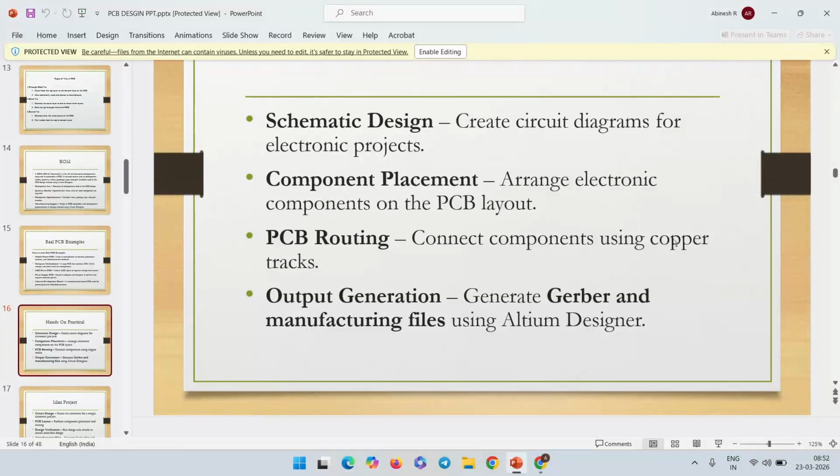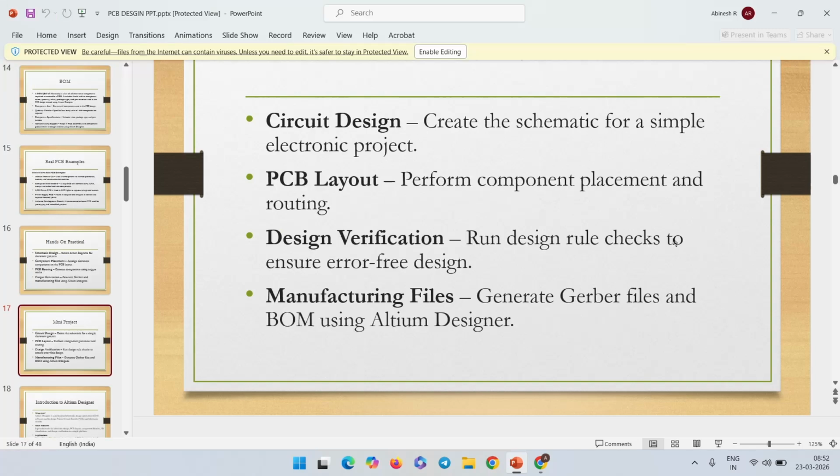Okay, after that you can generate an output file, which means a Gerber file, which is an output for our designers and an input to the manufacturing unit, which contains all the information about the different layers. Okay, so it is saying what the things are that you want to design.